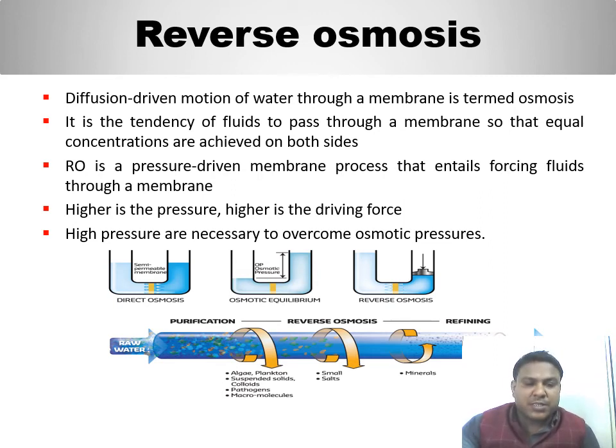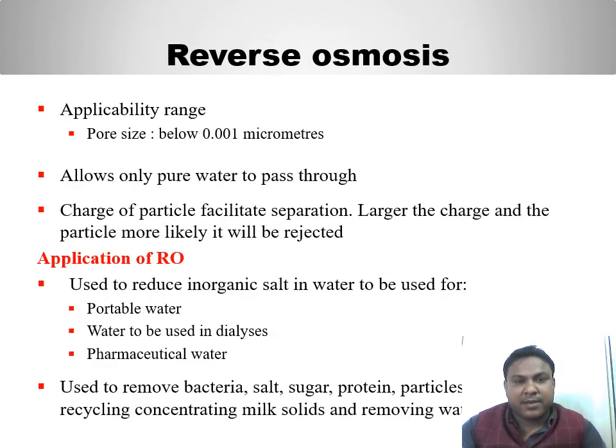So basically reverse osmosis is the most complex technique in membrane separation. Although reverse osmosis is recognized as a leading technology in the desalination process, it is also a well-established application in food processing due to several advantages over conventional methodologies, such as the preservation of thermally sensitive compounds, low energy consumption, and low investment cost. Reverse osmosis operates with a highly compact membrane pore size, allowing particles smaller than 0.001 micrometers to pass through. High pressure of about 30 to 60 bar is required in order to overcome the high osmotic pressure across the